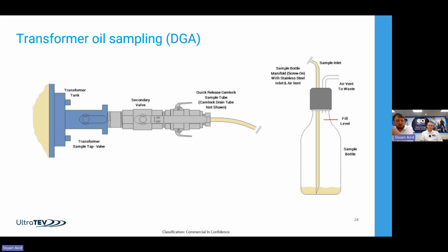It'll let you trend the age of the oil and the degradation of the transformer over time very well, and will give you plenty of time and headroom and some service options in terms of replacing the oil, refreshing the oil, which allow you to extend the lifetime of it. So if you're not doing DGA analysis, it's worth looking into.